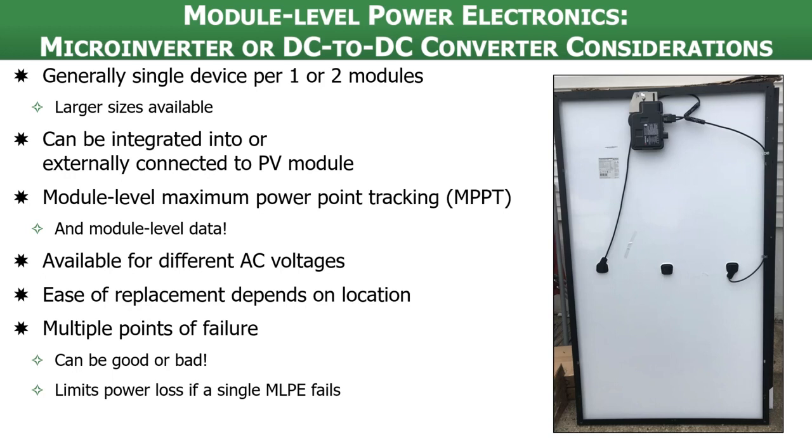with different problems on different inverters, different microinverters or something along those lines, and that can make it a little more complicated for troubleshooting. But it can also be a good thing, because if you just have one microinverter that happens to fail, it's not necessarily going to impact the performance of your entire system. You may have a situation where one microinverter fails, and that may still mean that part of your system can continue to function unaffected.